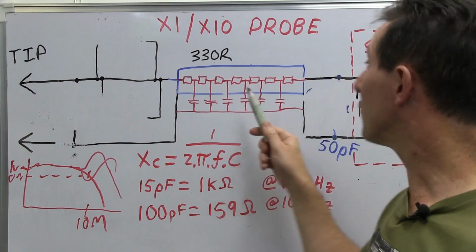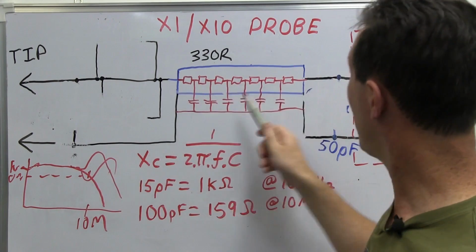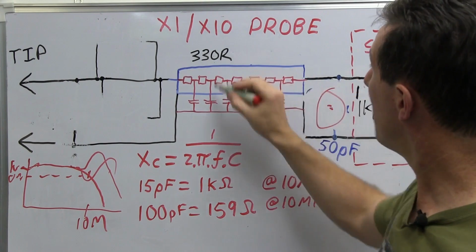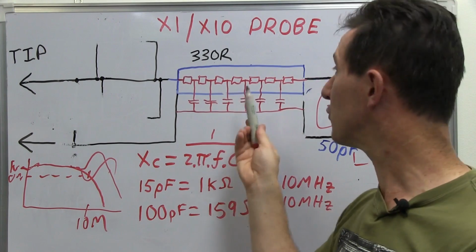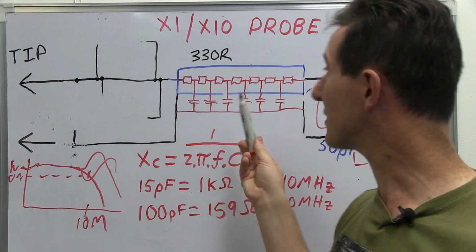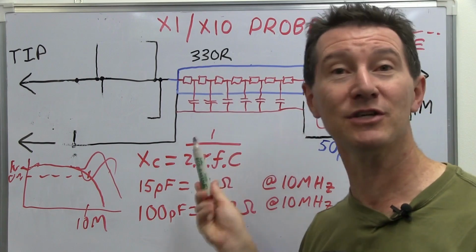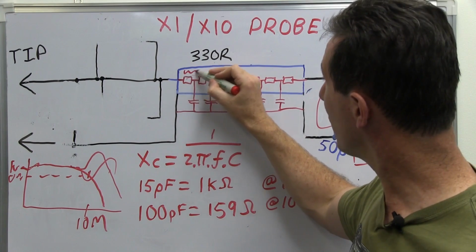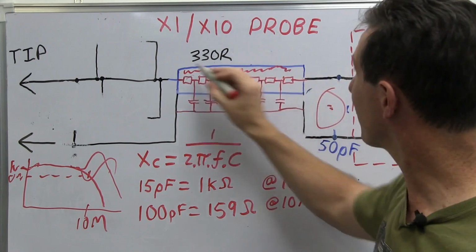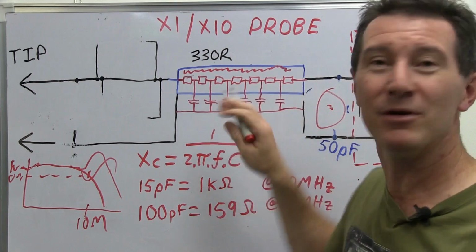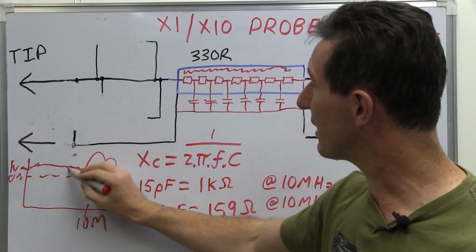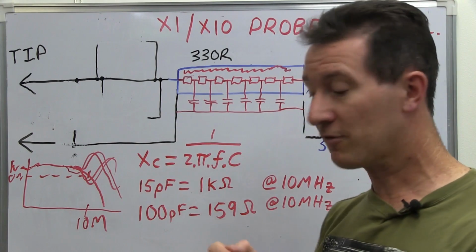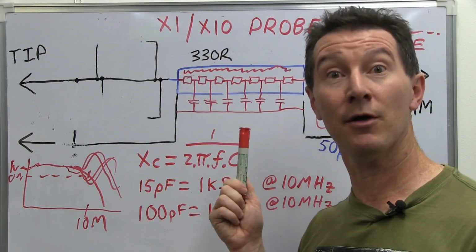They're very difficult to actually get right, and to trim and get it all right in terms of the compensation network in here that we looked at, matched to the actual physical properties of the coax. So a lot of art and science goes into designing the physical properties of that cable, getting that little wiggle inside exactly right, getting the lossy parameters all right so that they match, and you don't get any funny business, overshoot, undershoot at the end of your bandwidth and all that sort of stuff. That requires a whole separate video though.